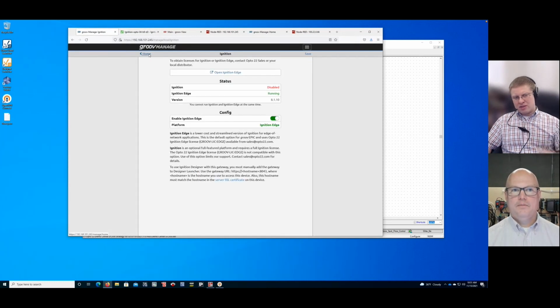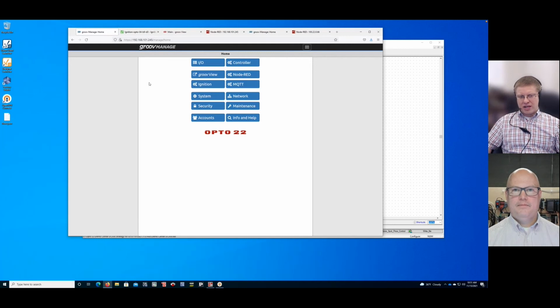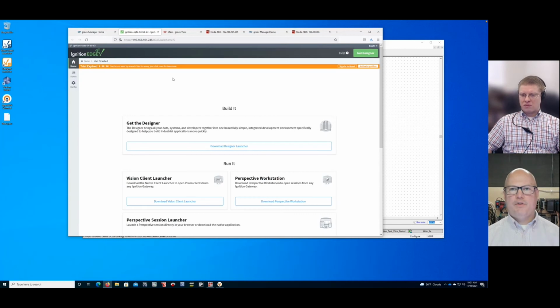And I guess just to rehash kind of what you said, then Ignition Edge is basically functionally an edge gateway for legacy protocols that then translates into MQTT as it publishes upstream. Is that right? Yeah, it can. Yeah, absolutely. I mean, there's several flavors of it. It's an edge HMI. So you can do some screen development and that type of thing in it. But like I said, it's an Ignition Edge instance. It's running right on the device itself.